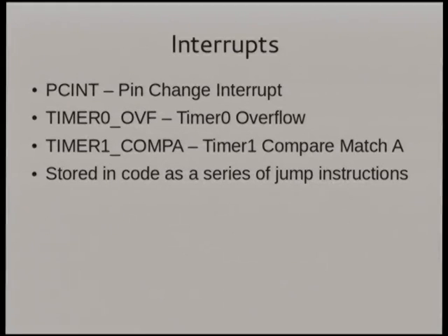And here are some examples of the interrupt names that you might find on an ATtiny85. So PCINT, pin change interrupt, TIMER0_OVF, so timer 0 overflow. There are multiple timers on these chips, and they've all got numbers the same way that the ports all have names. I'll get to the timer things a bit later. In the actual flash, they're stored as a series of jump instructions. So it's just jump to this function, jump to this function, jump to this function. When an interrupt is generated, it jumps to the appropriate part inside this table, which then has the jump instruction, which jumps to the right place in your code.